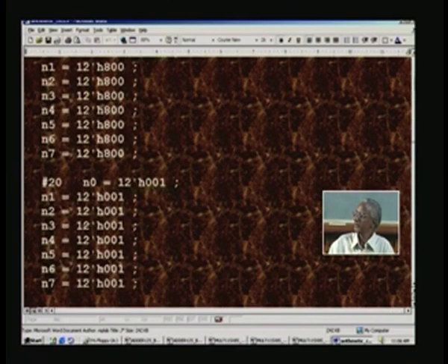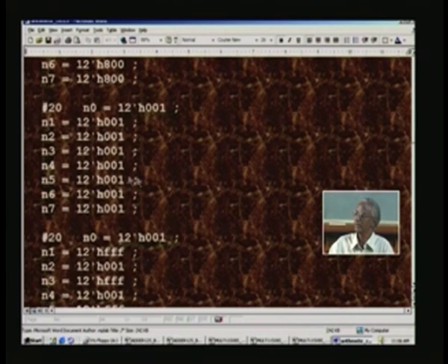I am sorry, I mentioned 100 megahertz, but it is actually 50 megahertz because the loaded value is only 10. So, that is only half the time period, therefore, it must be a 20 nanosecond time period, and hence the clock will have to be 50 megahertz.